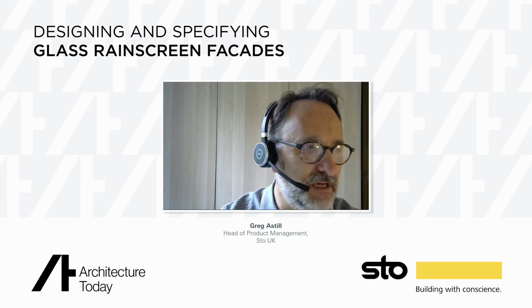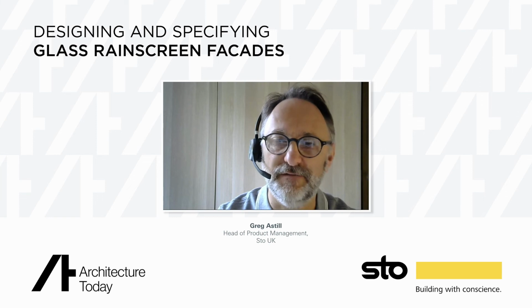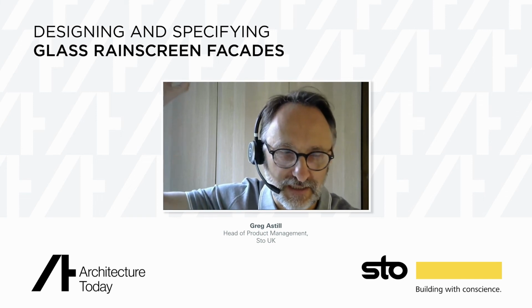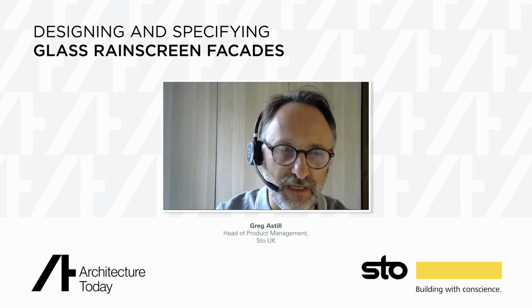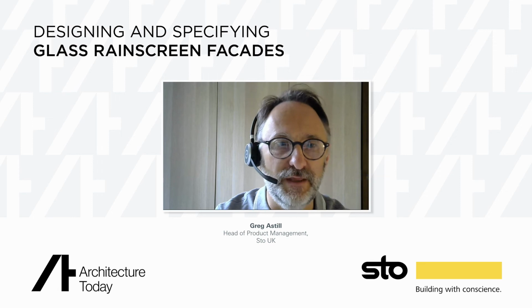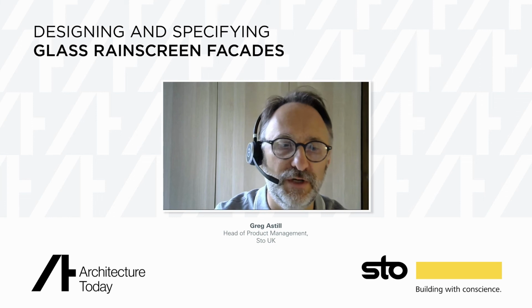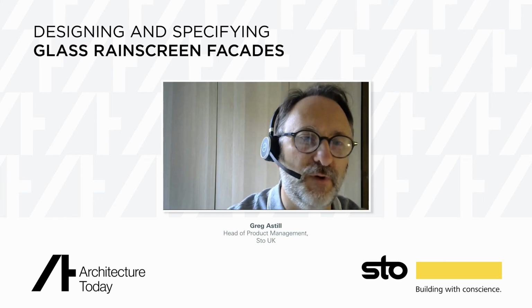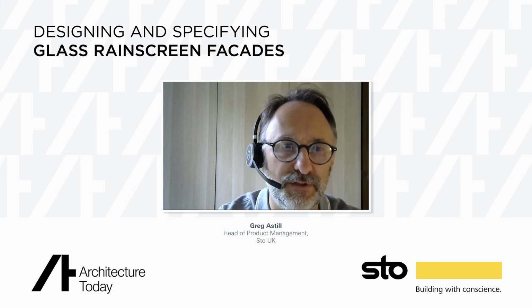So you're swinging something like, I think it's a 50 kilo medicine ball at its highest. That's probably the highest one, the soft impact. Funnily enough, it's a 50 kilo medicine ball being swung from, I think it's about 1.2 meters away, at an angle that starts at 90 degrees, and so swings down into the glass itself. What's being measured there is the damage that occurs when those impactors hit the glass, whether it damages the panel or not, but also more fundamentally whether any parts fall off and could therefore cause harm to anyone down below.